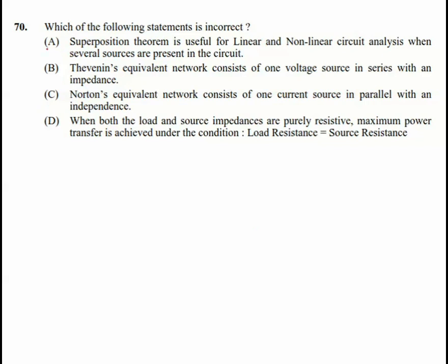Okay, and the last question of this session is: which of the following statements is incorrect? Here the superposition theorem is useful for linear elements only. It's not valid for non-linear elements. So this statement is not incorrect. It is used for analysis when several sources are present in the circuit. And Norton's equivalent network consists of one current source in parallel with an independent impedance. Actually it should be impedance, so this is a spelling mistake. You can also choose this one as per the key given by APTRANSCO. So the first option, A, is the option here.